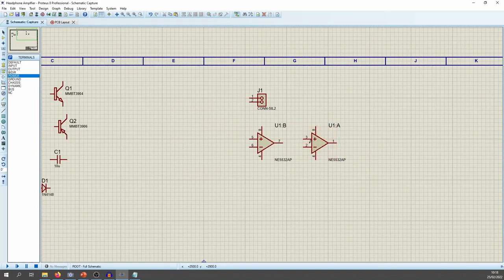As Joe says, when you've got a chip that's got loads of power rails, then with all the decoupling caps, you can put them neatly somewhere. So like that then. So the decoupling cap's there, but that IC. That's what I tend to do. Yeah. Okay. Or put them in a corner somewhere and label them with a bit of text or something. That's what I've tended to do.